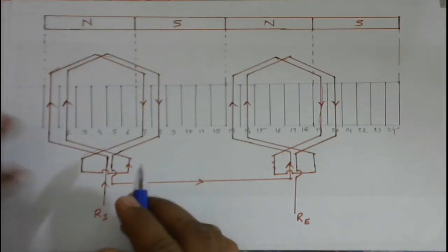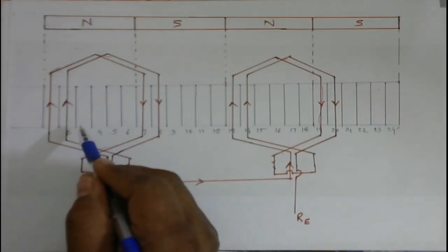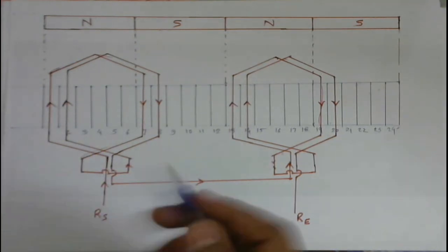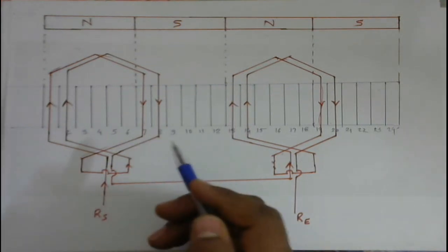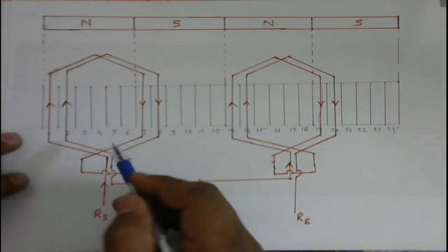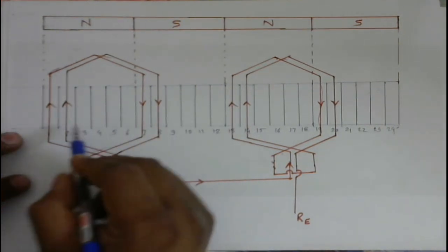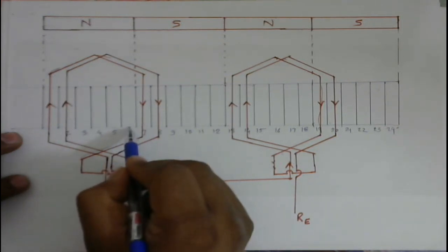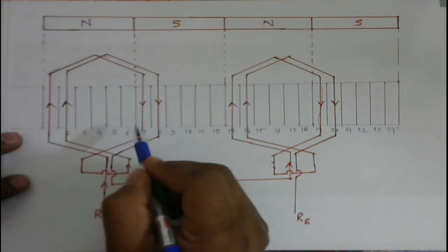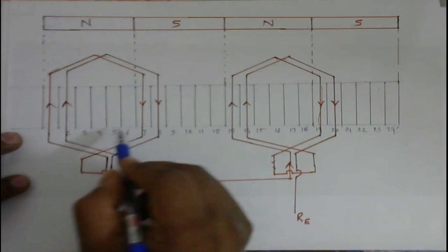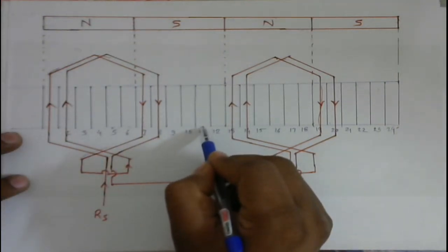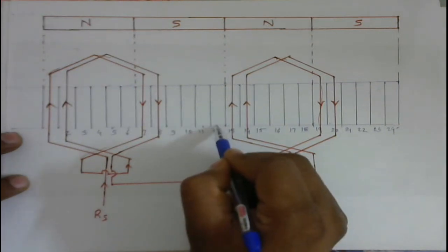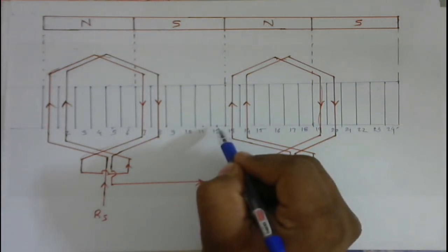See, generally you might be thinking why I'm not drawing the diagram for B phase, but B phase will be drawn afterward. As per the previous session, I told you why to put Y phase winding in the 5th and 6th slot instead of 3 and 4, because we have to maintain the 120 degree phase shift. So accordingly, from 5th we'll proceed to 11th, and from 6th we'll put winding in 12th.